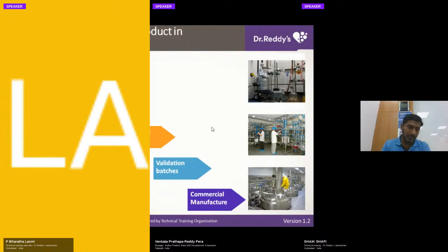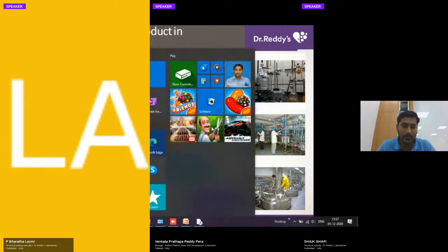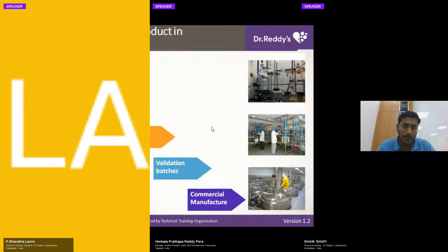This is a very important one. So there is a lot of things that need to be discussed here. So any new product comes into a plant. Before starting manufacturing operations, what we do is lab trials first, then followed by pilot trials, then followed by the plant trials, then coming to validation batches, then coming to regular ones. So lab trials means this we conduct at R&D stage, research and development stage.